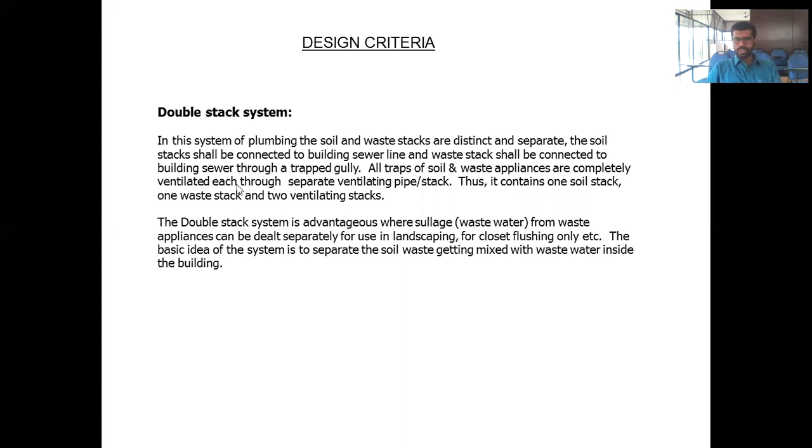All traps of soil and waste appliances are completely ventilated, each through a separate ventilating pipe or stack. So we have to give a vent through a separate ventilating pipe for all the fixtures and traps. Thus it contains one soil stack, one waste stack, and two ventilating stacks: one ventilating stack for the soil stack and one ventilating stack for the waste stack.